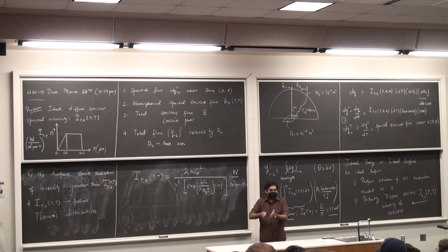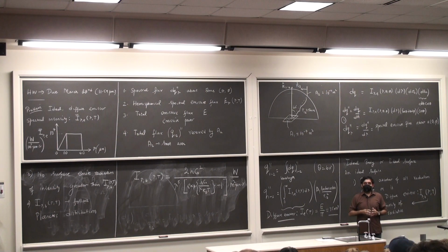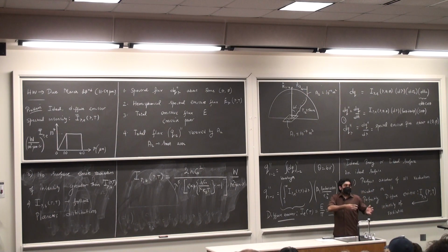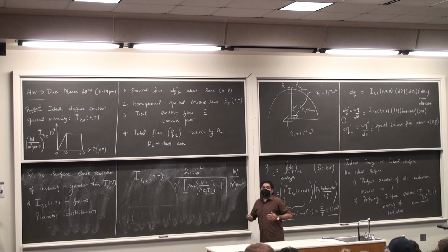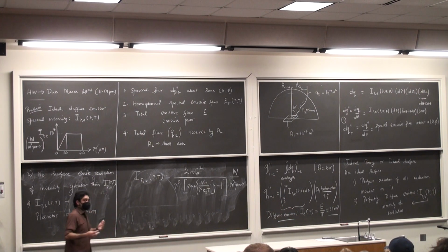And so I multiply this value by that particular fraction, which is called your emissivity. And I get I lambda comma E for a real surface. Once I have I lambda comma E, as you see in our problems, you can calculate the emissive power or the emissive flux, do the same thing for irradiation. I get Q net radiation, or the net radiation flux, which is all that we are caring about.